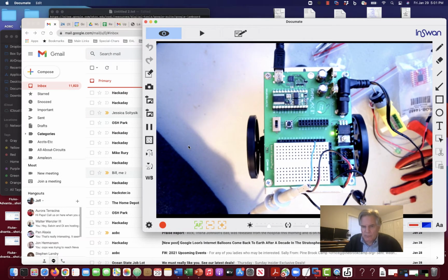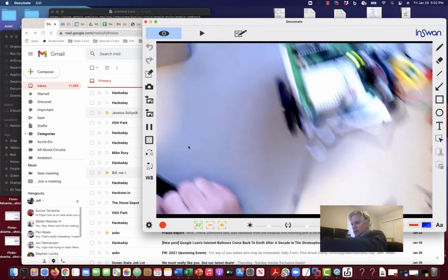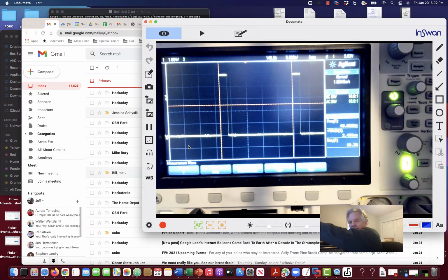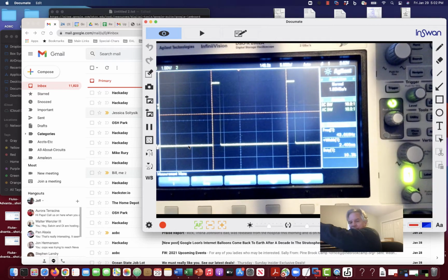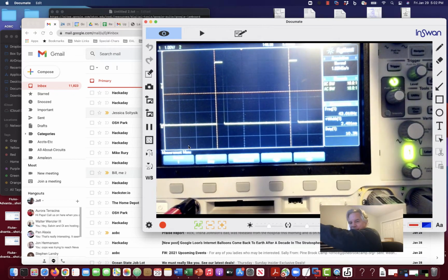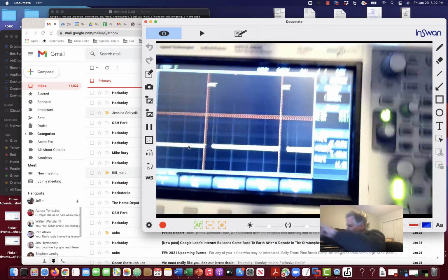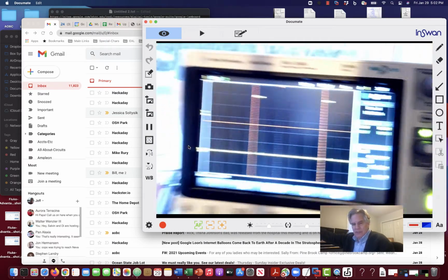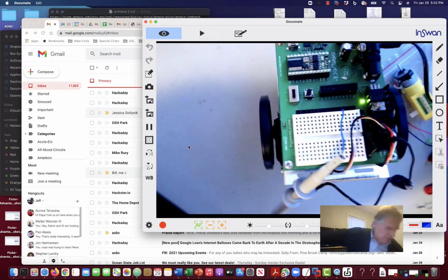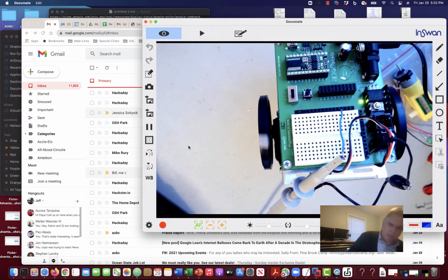And you can see the motor is moving much faster. Okay, making a lot more noise too, but it's moving faster, and the pulses are fatter. If you look at this, we'll see that we're up above 10. This actually says about 10.3% duty cycle, and 2.4 milliseconds, and actually the overall frequency went down a little bit. That's supposed to be pretty much constant, but the more important thing is the duty cycle.